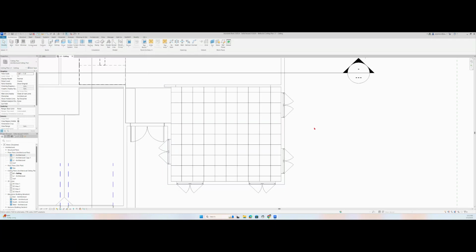Like on the previous video, the previous short, to get X-ray vision powers, the way to enable them is by going into our properties, into our underlay, and change the range base level from none to level one, so I can see everything that is below that ceiling. So I'm going to be able to see my sofas, my coffee table, and I can start placing lights or a ceiling fan. Got it?